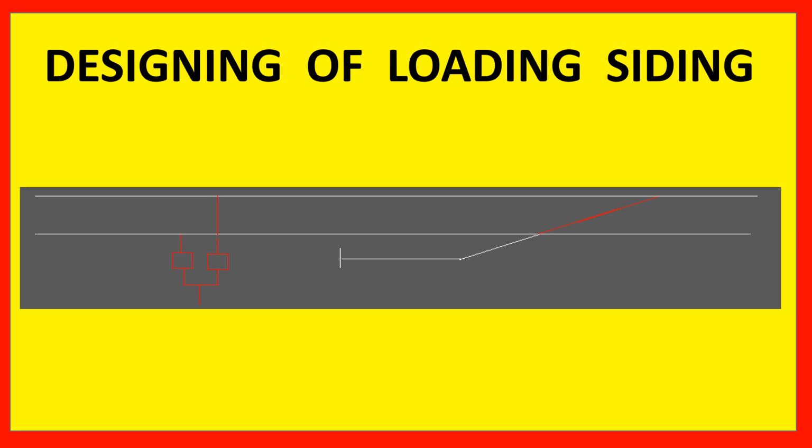But if you keep it in manual isolation, then it will harm. It will take time and main line will be affected for more time. So nowadays we are using circuit breaker to feed the siding line, and as standby supply means an isolator to the turnout point of the siding with sectioning arrangement.